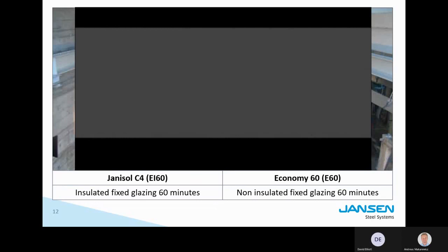I'm following. I mean, protecting a building from a fire is really a more complex task than just choosing the elements. You have to know the, let's say, the number of occupants. You have to know the size of the corridors, size of doors, distance between the doors which you have to open. Lighting and so on. So there are many factors that will determine which class you should use.